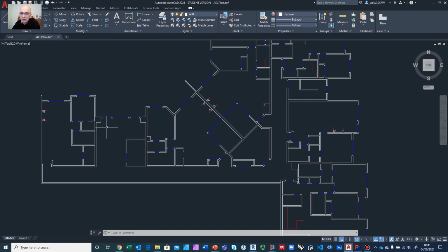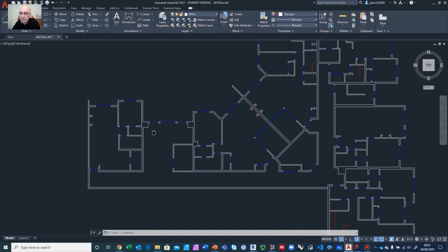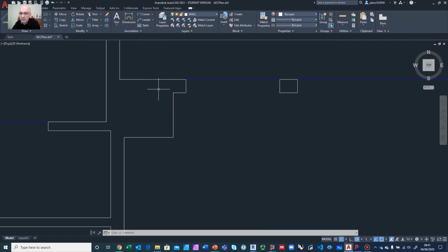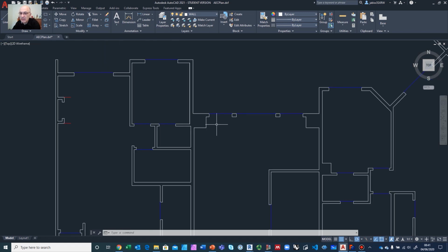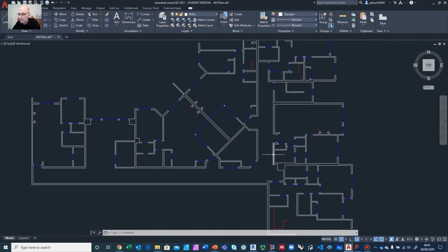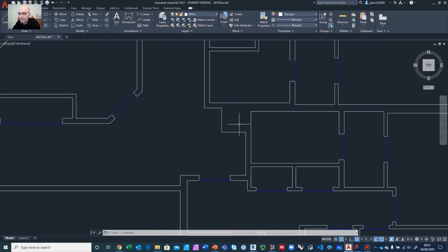The last thing I did, which was just for convenience, is some of these pillars, I call them, like what you see here, this one here, had an actual rectangle inside of it, so it was hollow on the inside. And that would have created another circuit and another wire, independent from the other ones. I just wanted the wires that I'm interested in, as if I'm going to laser cut this. I didn't want the hollow piece in here, so I deleted these rectangles from this pillar, this pillar, this pillar, and I think there was another one over here somewhere. Yeah, this one here, right there.